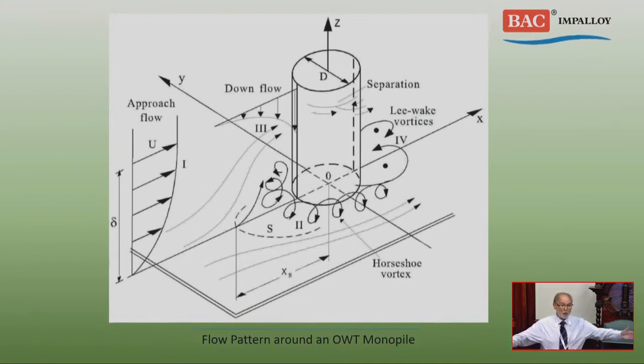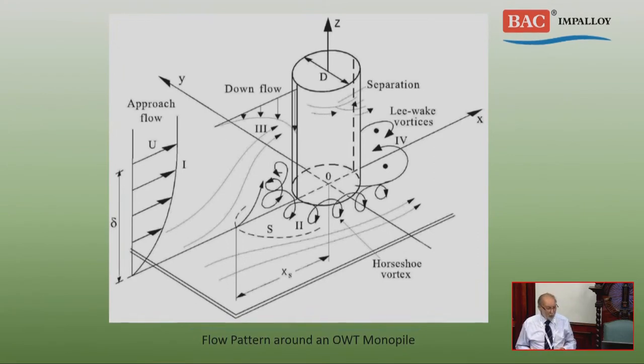As the water goes round the monopile, it has to join up at the other side, otherwise you'll get a void. So it has to increase its speed around. And there are all sorts of turbulence factors as well. And the new ISO for offshore wind farm CP does take this into account and makes some recommendations about the effects of water velocity on the current density. So we are making progress. We are making some effort to be cleverer in our CP designs.